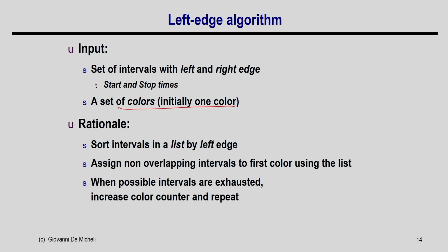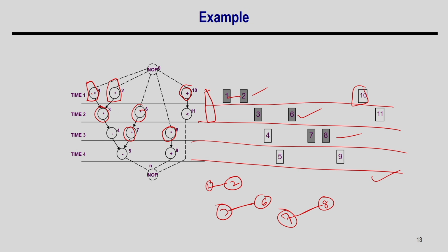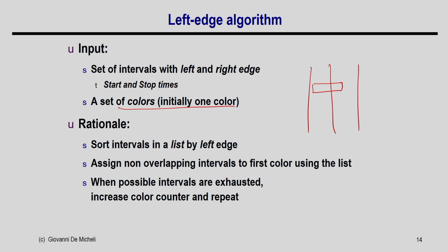Now, the question is how I am going to represent the intervals. The intervals are represented for this algorithm as a left and right edge. So, if you see here, if I just say this is my time, in the previous example it was in the top to bottom direction, now I am going to make it left to right direction, you can always rotate it.